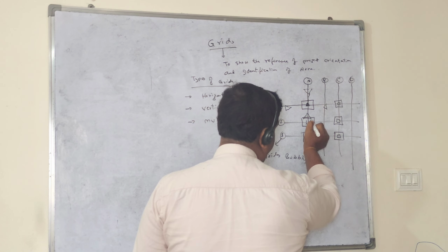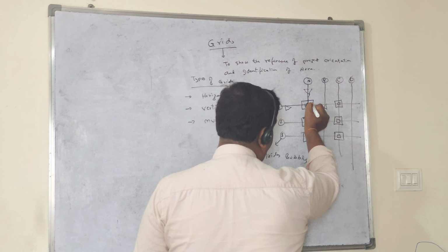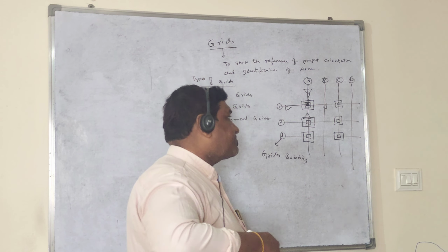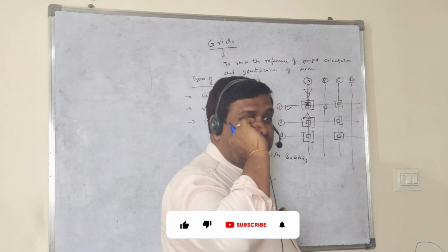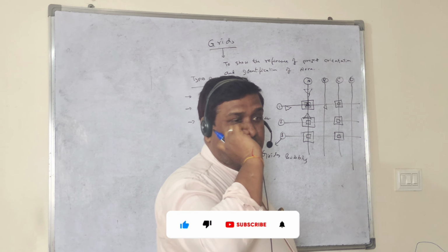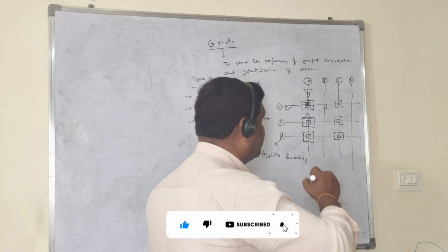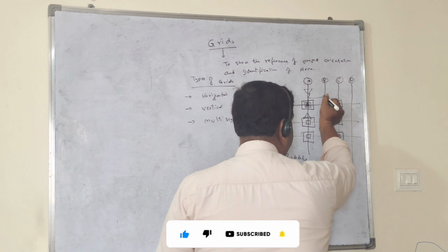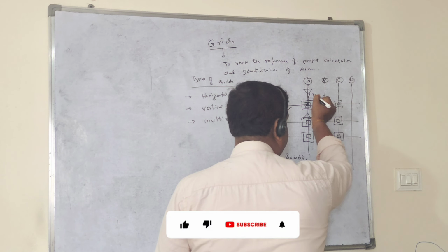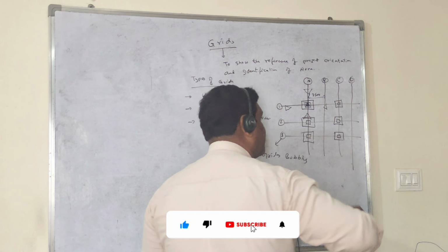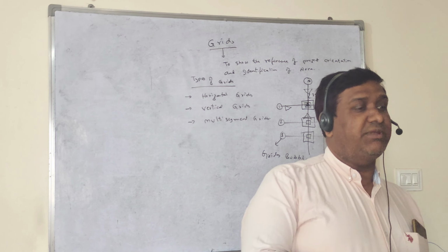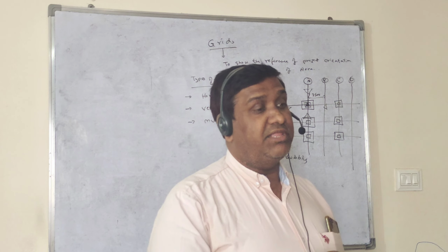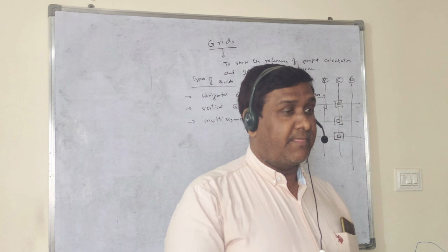So before designing the project, you have to identify the project orientation. Based on the orientation, decide where the grids have to be placed. What is the distance? Because from grid to grid there will be a distance. The minimum distance is 3500 mm, because from one foundation to another foundation there should be a minimum distance of 3.5 meters.